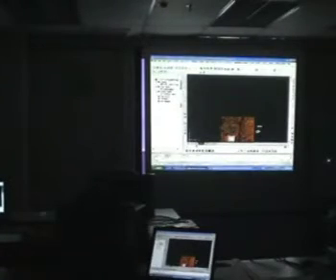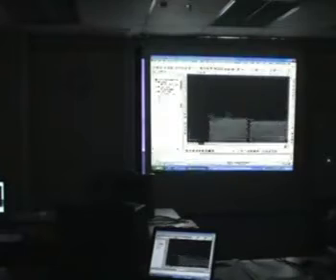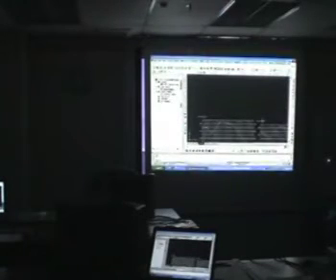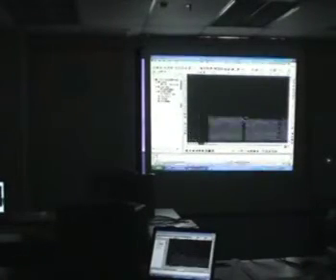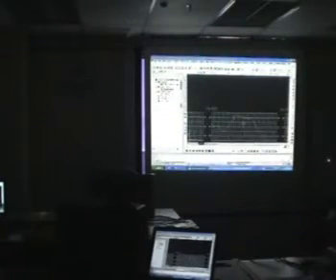The interval which I have set is dependent on the grid value which I put in during the site definition. In this case, I put 1. So if I zoom into the sections, you can see that each interval is 1 meter. It can go as small as you want, but here these are 1 meter intervals between each other. At the moment, it's taking 1 meter from the border.